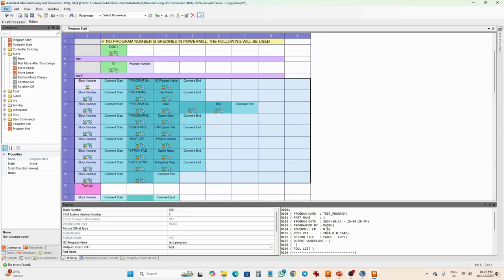These instructions tell you what type of tool is being used, either tool number 1 or tool number 2, what is the total length of the toolpath, and how much time it is going to take. So this will help you a lot. That's what we call the program start.